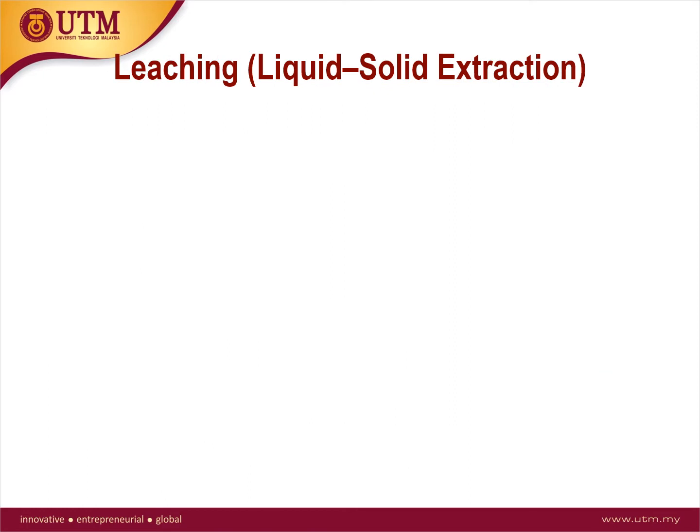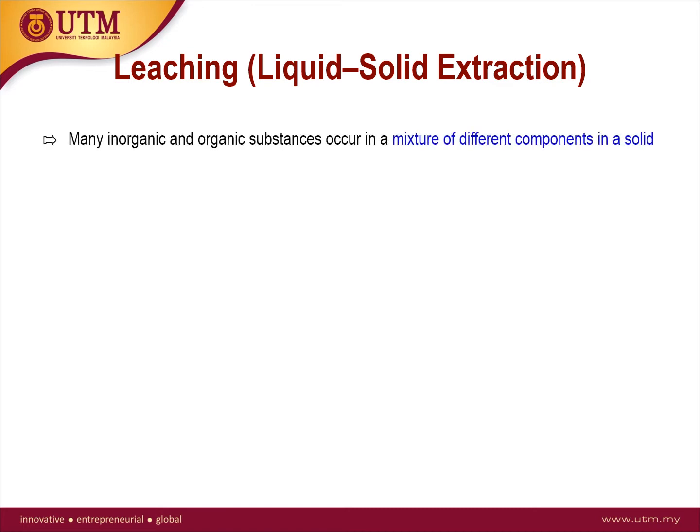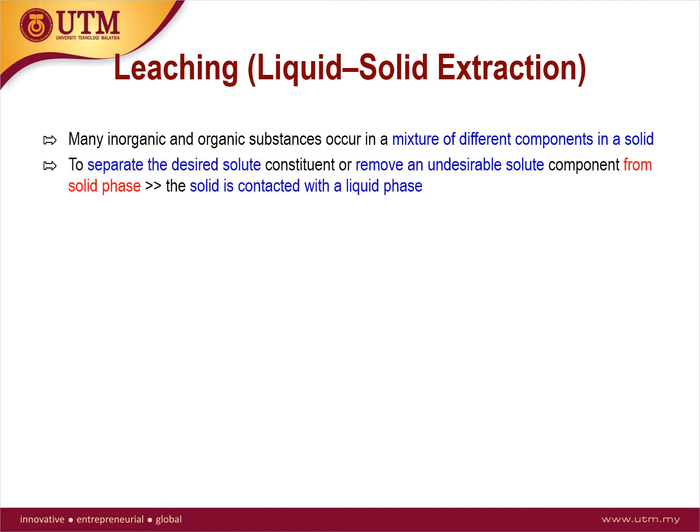Besides liquid extraction, we are going to learn about the separation of liquid-solid extraction, commercially known as the leaching process. Many inorganic and organic substances occur in a mixture of different components in a solid. In order to separate the desired solute constituent or remove an undesirable solute component from the solid phase, this solid phase is contacted with a liquid phase that is normally known as the solvent.